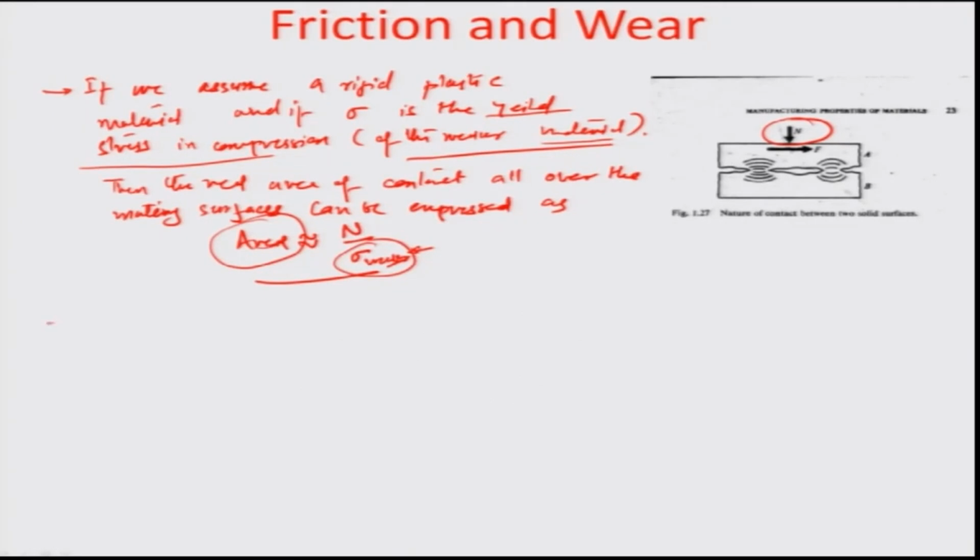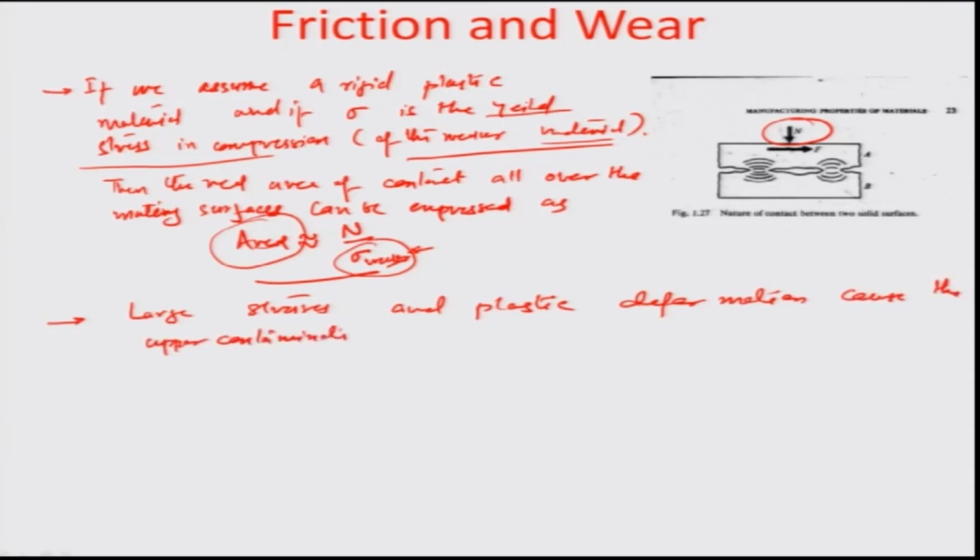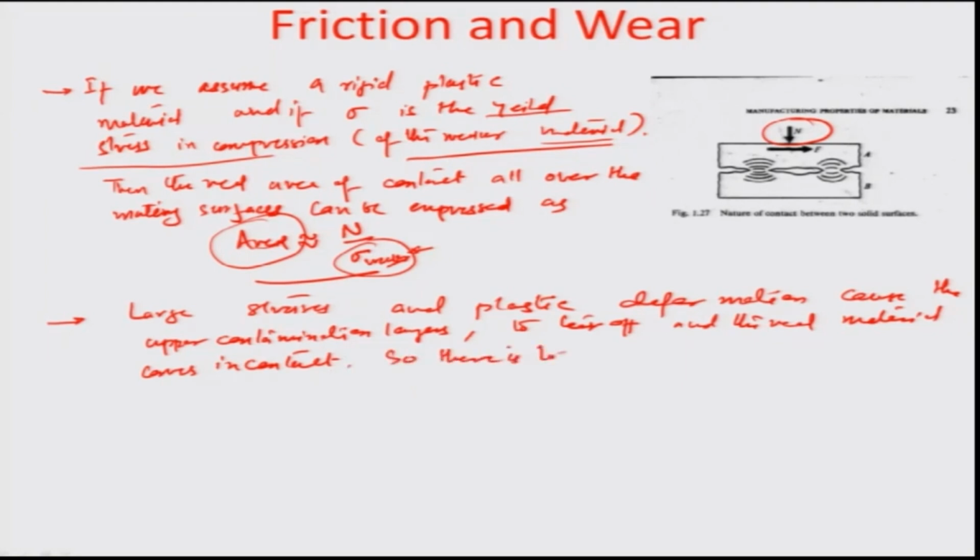So large stresses and plastic deformation cause the upper contamination layers to tear off, and the real material comes in contact, so there is local welding.